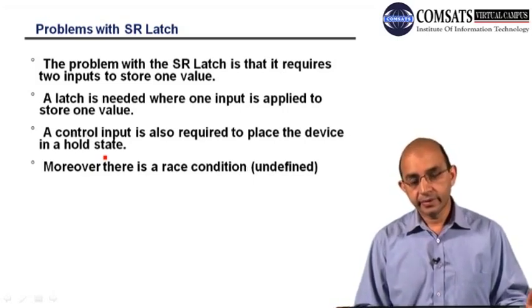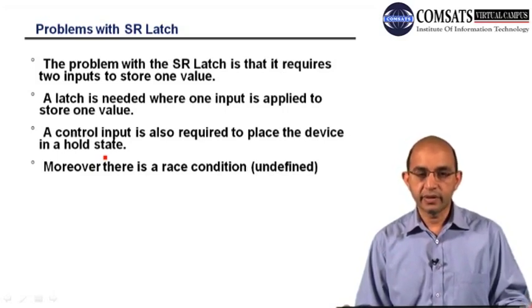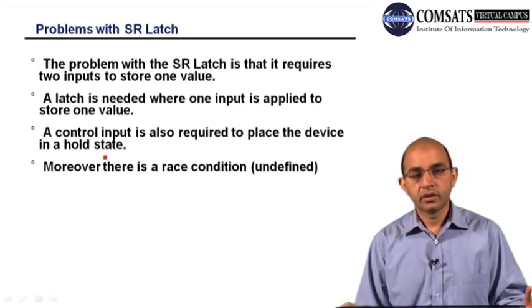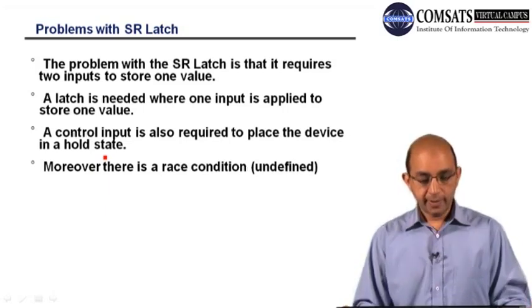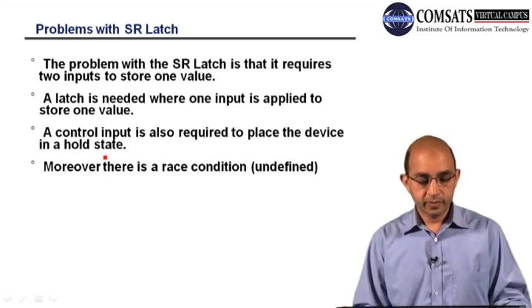And finally, there is a race condition over here. Like in the case of the NOR latch, we have to avoid 1 1, and in the case of the NAND latch, we have to avoid 0 0. So these are the problems.